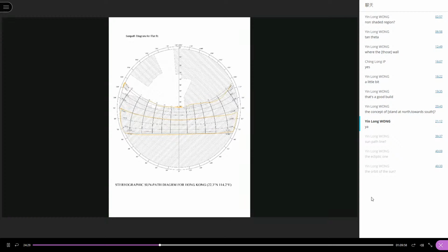I know that in your assignment, you have to make a site visit to some buildings in Hong Kong and then try to plot the obstruction and the external shadings on the sun path diagram. In this tutorial exercise, I have taught you how to roughly plot the external obstruction onto the sun path diagram. So in your assignment, maybe you can try to do something similar.